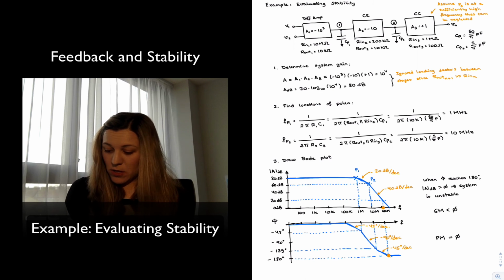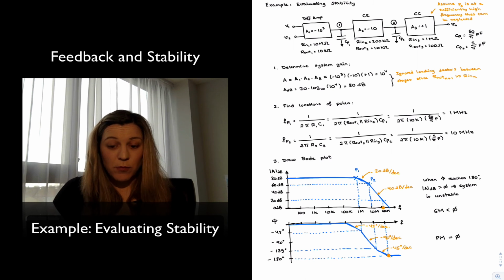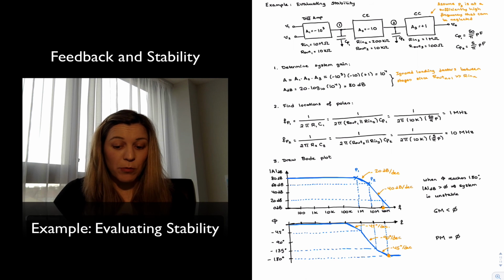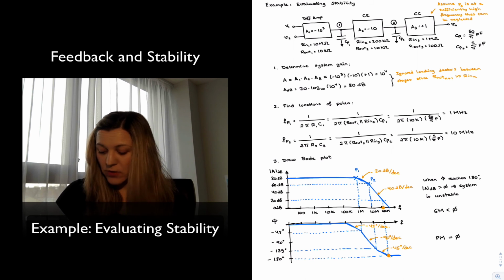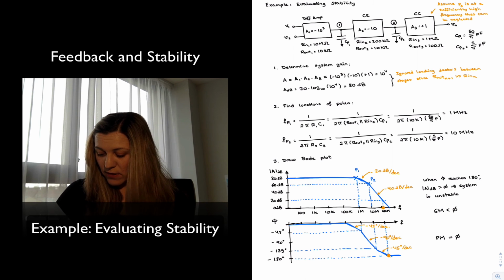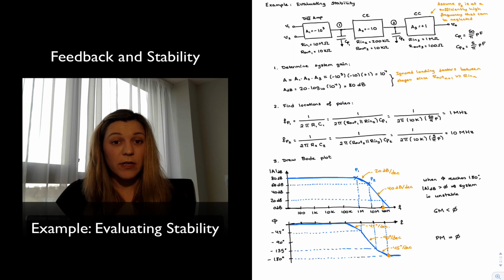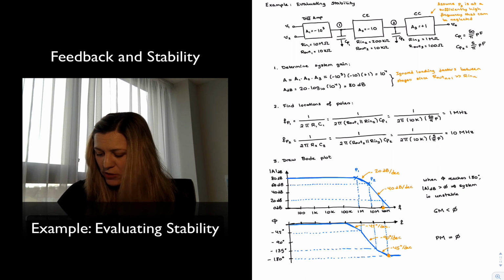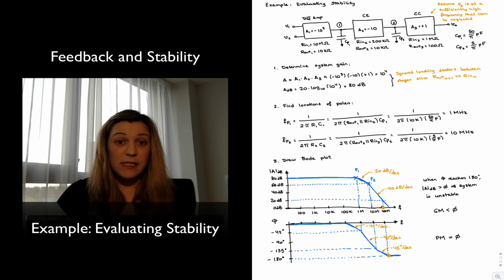Now I can try to make this system stable by changing the shape of the frequency response. That's what we term frequency compensation. There are different methods for applying frequency compensation. There's the method of adding a dominant pole. There is the method of adding a zero, and there is the method of shifting the dominant pole. That is the method that we know as Miller compensation or dominant pole compensation. Now one can see why that would be the case.